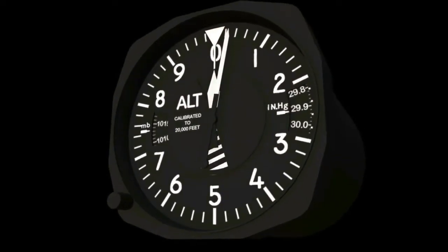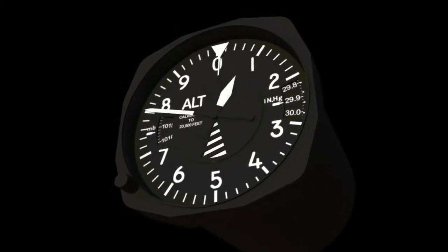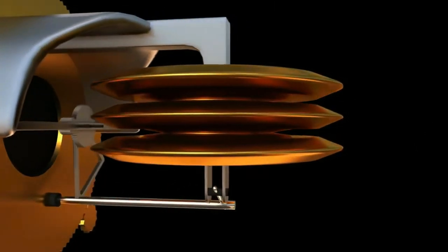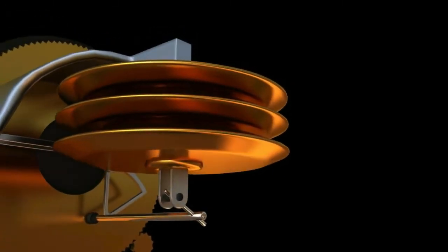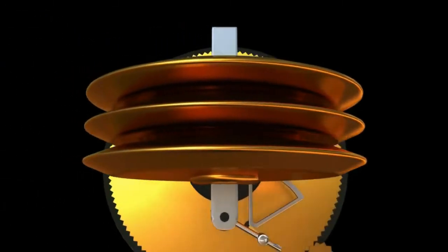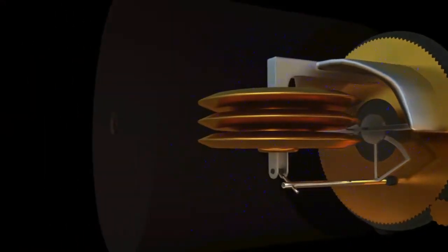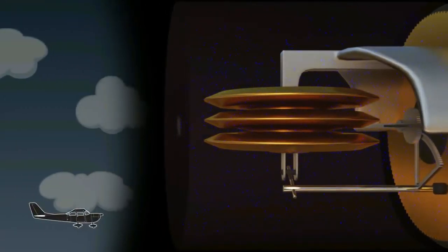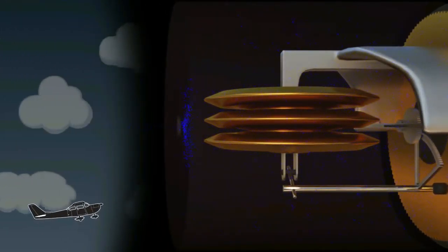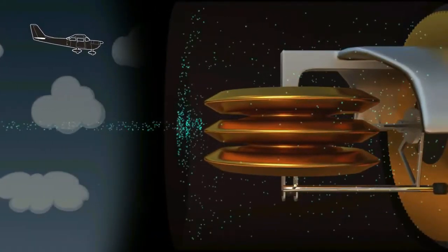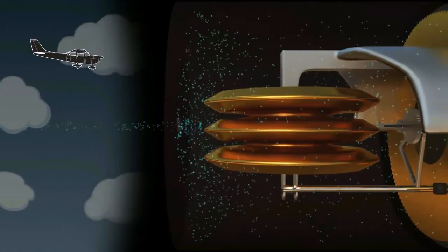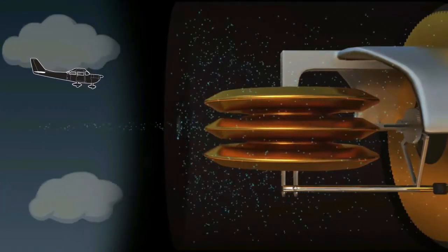An altimeter measures the height of an aircraft above a fixed level. I mean to say, the instrument senses this by taking the ambient air pressure from the static port. Inside the altimeter is a sealed disc called an aneroid, or we also call it bellows. As the aircraft goes up, the pressure inside the case decreases and the bellows expand. The opposite happens as the aircraft descends.